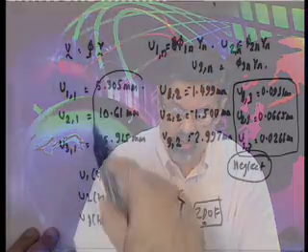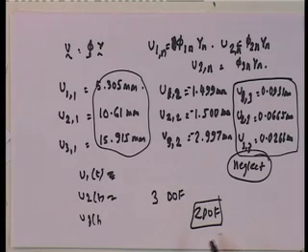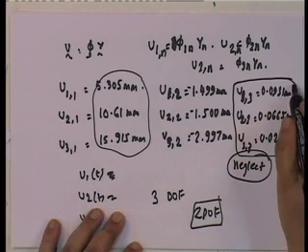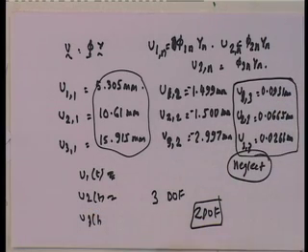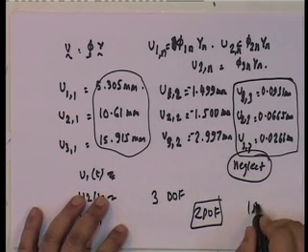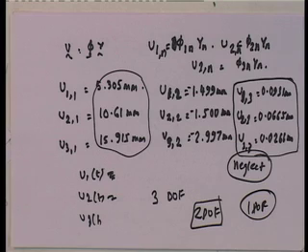Okay. If you do not have that situation, you will have a situation where the total will almost be given by the first mode. Okay. Here I actually caused a situation where the second mode contributes more, I made it. However, you still see that the third mode is to be neglected. Okay. So, in actual fact, in reality, if we just deal with a 1 degree of freedom system in this particular case, you will have solved the problem.